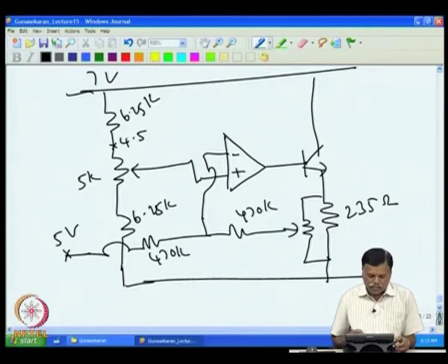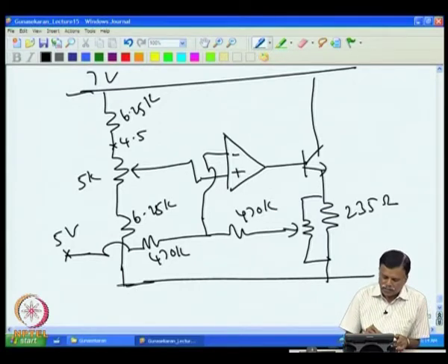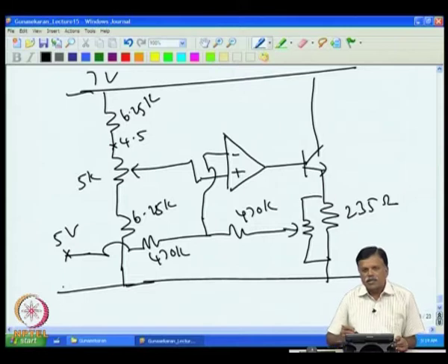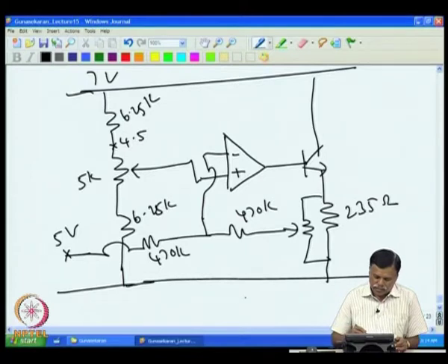So, this is our current converter stage. Now we have to calculate what are the errors involved in this, and then we also had to compute that error in terms of current that is flowing in this circuit. Now, if we take this circuit, first we take the simplest one, that is offset voltage drift of this operational amplifier, because this operational amplifier also will have offset voltage drift. So, if there is offset voltage drift here, then what is the current change here?